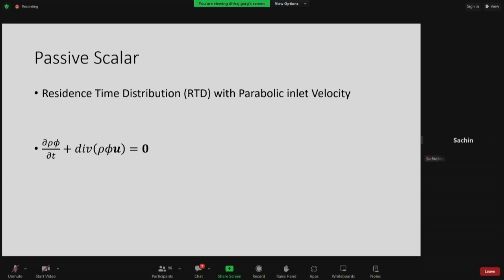The thing is, you are running initially for the velocity distribution, running the simulation without phi, let's say. No chemical injection before, no tracers, you are not simulating anything except your velocity profile. Once it is obtained, you take the last simulation as the initial condition. That means it is already settled, and you have already obtained the final distribution.